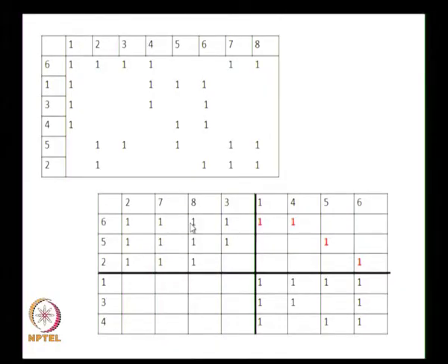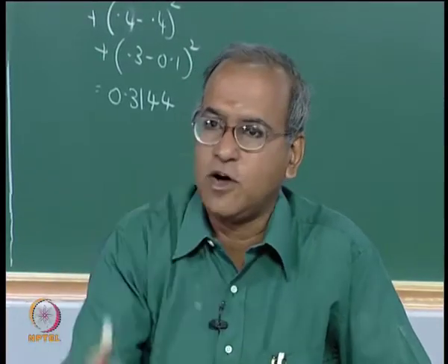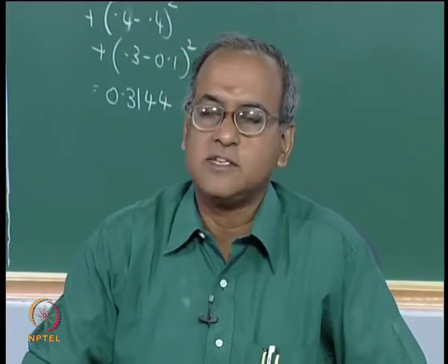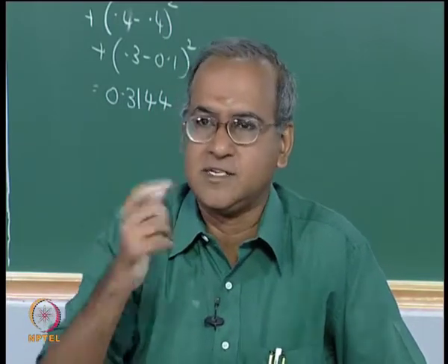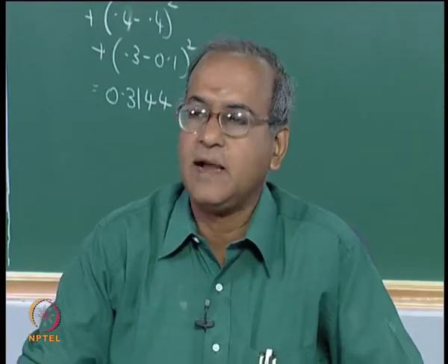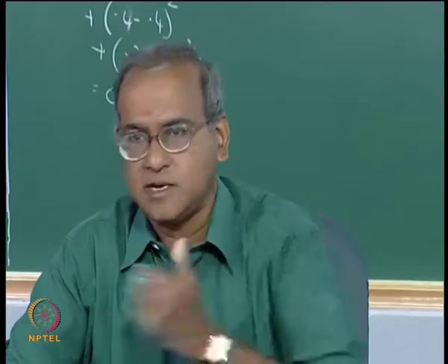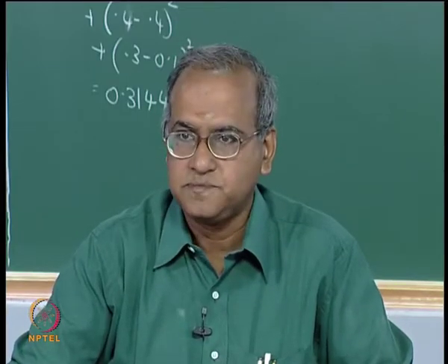So, this cell will have 5 parts, the other cell will have 3 parts. Now, the alternate process plan again has to be looked at based on 2 considerations. One is the existing plan, which again would be a common practice, what is currently being followed would be captured. The other is to look at, can we make some very minor changes in the design which will result in a change in process plan and move it to another cell where it minimizes the intercell move. So, that is another way of doing it.